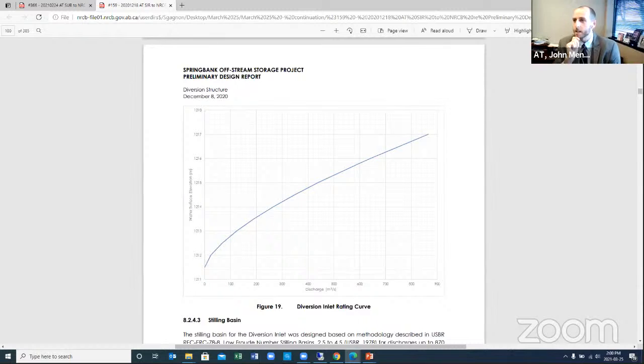Yes, intentionally so. But as I said, that's for when the water is at 1215.5 at the bridge. That's not what this curve is referencing. This curve is referencing a point upstream of the bridge that's away from the influence of the drawdown down and through the structure. So the hydraulics here is important to note. And so it is not restricting flow at our design flood elevation of 1215.8.